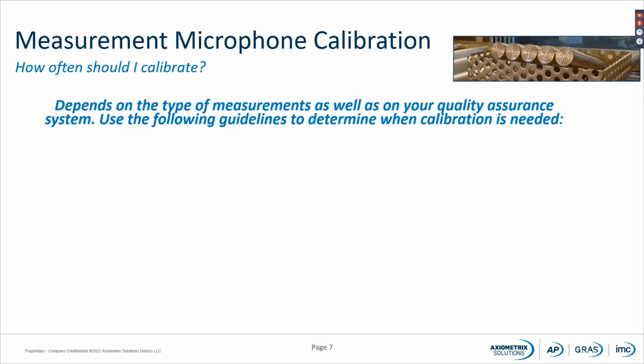Below, I will give you some guidelines to determine when calibration is needed. When you receive a new instrument, a new microphone, a new analyzer, whatever it is, it's a good idea to calibrate the new unit, to ensure that it is fulfilling its specifications and also the requirements for the measurements you would like to use it for.